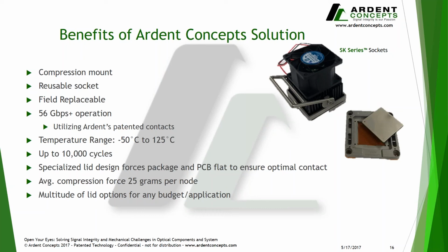Also, with this really large package size, our lid assembly ensures that the package is pressed flat and the PCB is conformed flat to ensure optimal contact. So it's very reliable and there's no opens. Another way that we're making sure there's not too much force added to the package is through our contact compression force, which on average in these designs is around 25 grams per node, which is pretty industry standard.